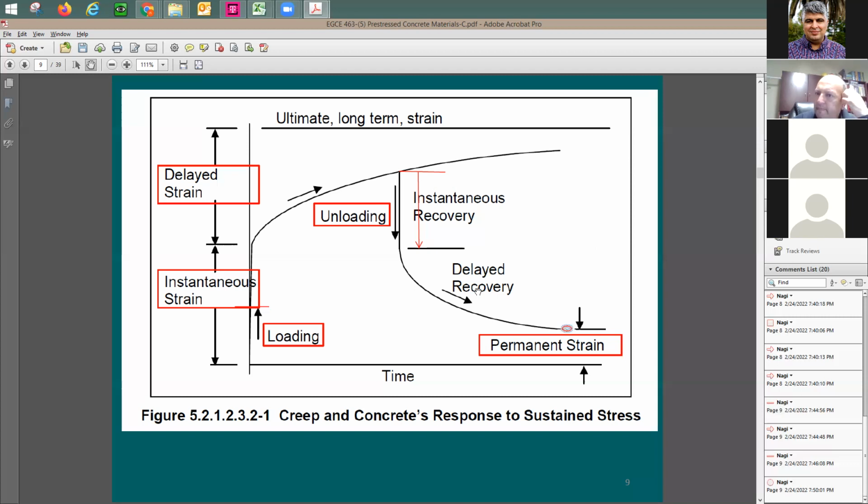With seismic, is there more of an emphasis placed on the performance at the joints instead of the entire member? Yeah, because the joints are going to have the higher stress. Let's say in a beam, right? Where is the maximum moment if you have fixed ends? The reaction. It's going to be at the end. So this is why the connection is going to be very critical, right? You're absolutely correct.